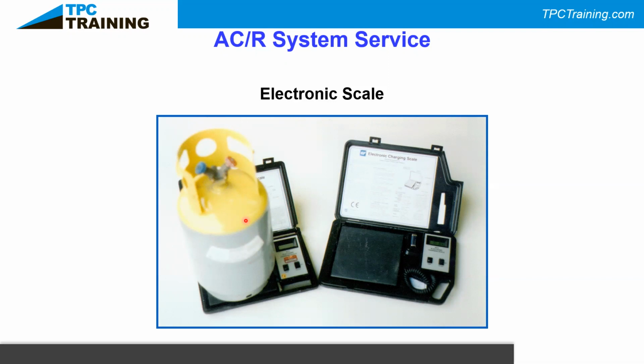Here's one thing I'll tell you. If they come to you, they've never been there before, and they say, you're low on refrigerant, but I've got some in the truck, and they bring this cylinder out, that means they're selling you refrigerant that came out of someone else's unit, and it has not been purified. We don't know if there's acid in there. We don't know if there's non-condensables in there. So send them home, get them out, tell them, hey, I don't trust you. It's okay to do that. There's plenty of contractors out there, and unfortunately, we're flooded with ones that don't want to do their jobs properly.